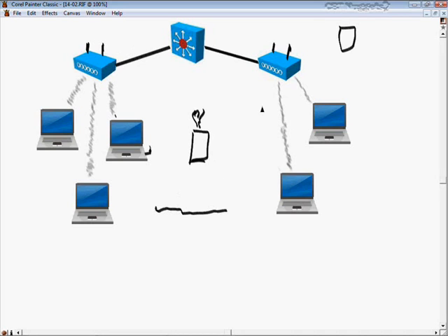Now, there are some rules for data transmission over RF. If you have a higher data rate, you'll have a shorter range because the receiver needs a stronger signal with a better signal-to-noise ratio, SNR, to receive the information. If you have higher transmit power, that'll result in greater range. That's governed by the FCC.